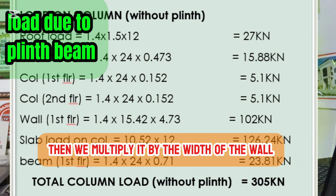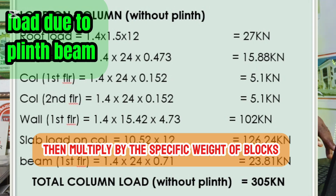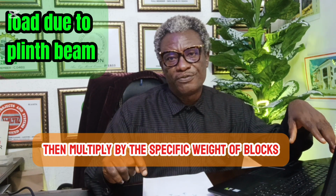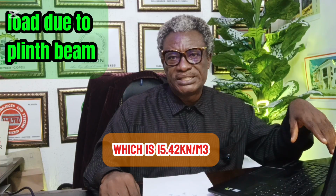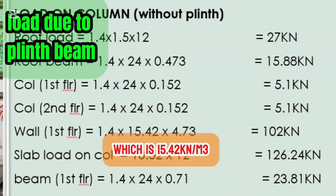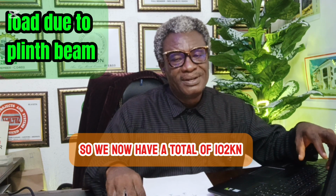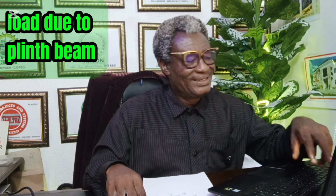Then we multiply it by the width of the wall, or thickness of the wall, which is 0.225. Then multiplied by the specific weight of blocks, which is 15.42 kilonewton per meter cube. So we now have a total of 102 kilonewtons.